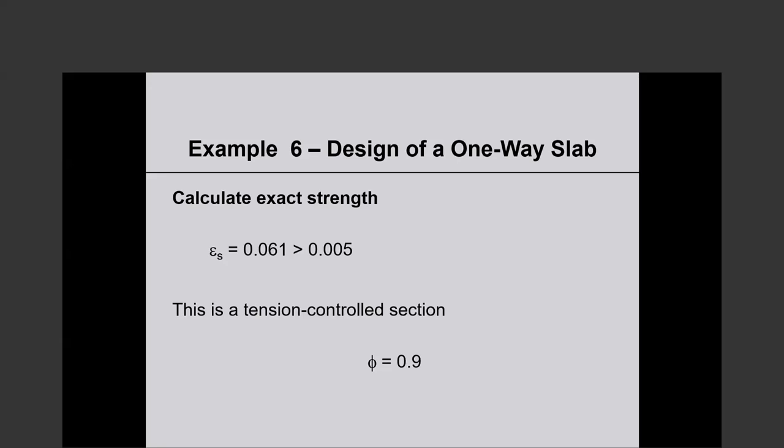So you consider the cracked section. That does not mean you use the cracked moment of inertia, which is a fraction of the gross moment of inertia. You use the effective moment of inertia. I had a picture, remember?